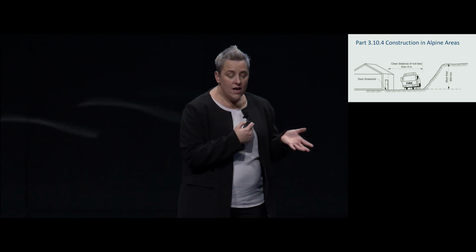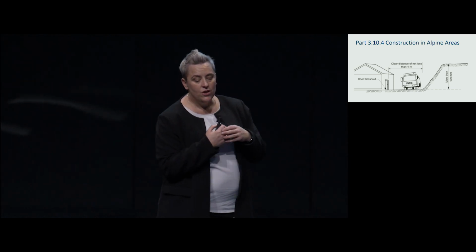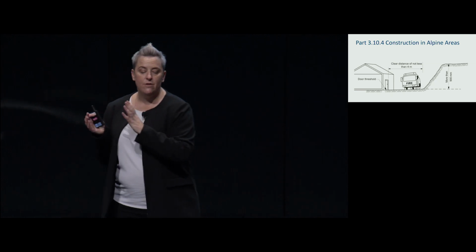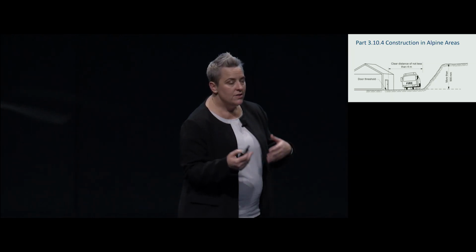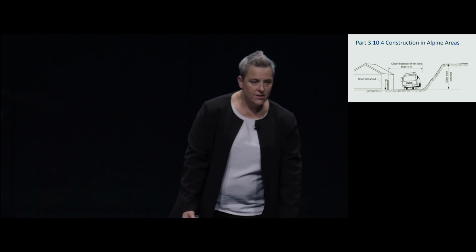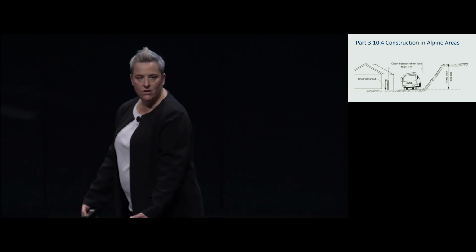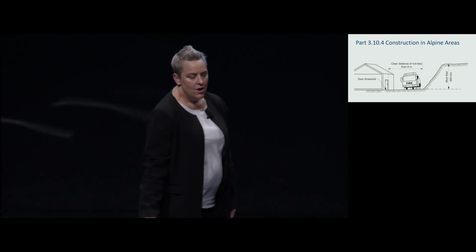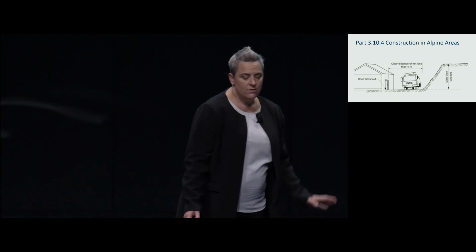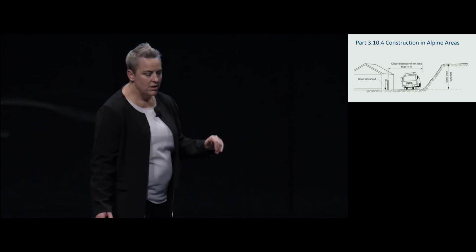Stair going and rising dimensions have been included, and these may be used instead of those specified under Part 3.9, because when you're in your snow boots and stuff like that, they're a lot clunkier and you have more trouble on a normal stair dimension, so they've allowed for differing stair dimensions.